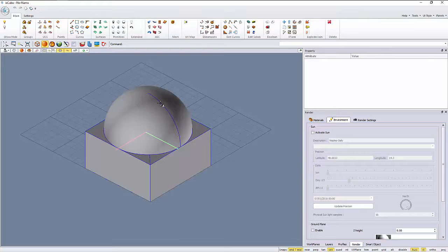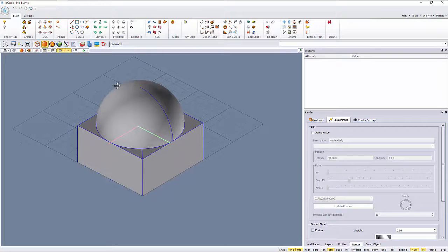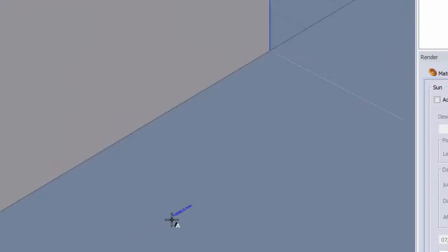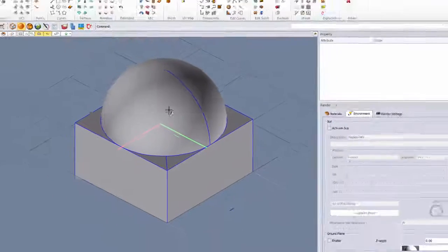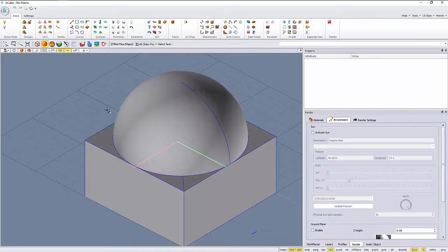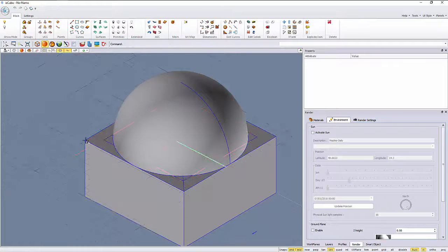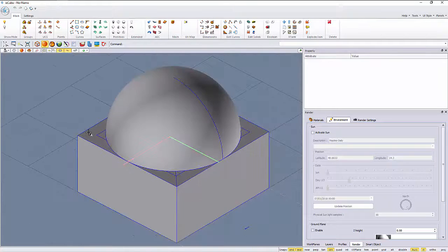I need to slice more my dome. It's still a full sphere, and I would like to underline that we have made the box 10 meters, right? 10 meters. But the room that we will cover will be 8 meters, because I'm going now to make offset face edges. This tool here, 1 meter, and so I have offset the face edges there.